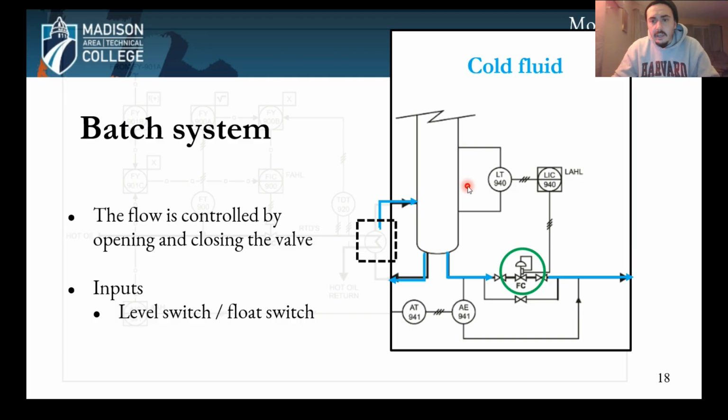This tells us, okay, once I've reached this point, fluid's up to this level. It tells the controller to open the valve and discharge the fluid. Now, if you have an array of those, you can have it discharge the fluid until it reaches the second one. So it looks like we have two here. So once the liquid reaches this level, I open up the valve and I discharge fluid until the liquid level comes back down here. Then I close the valve and I continue the process.